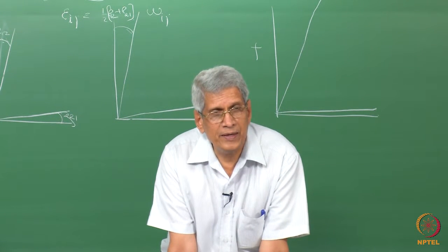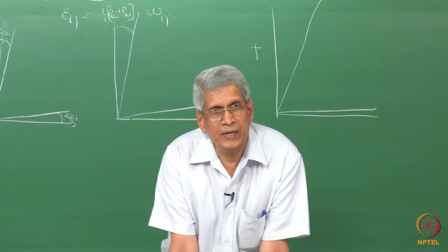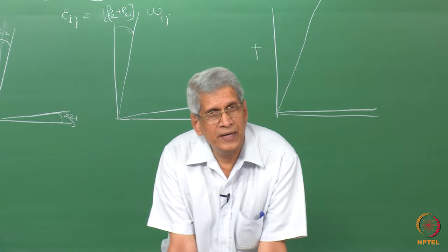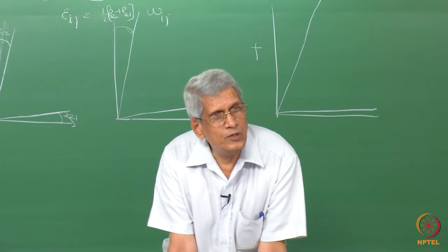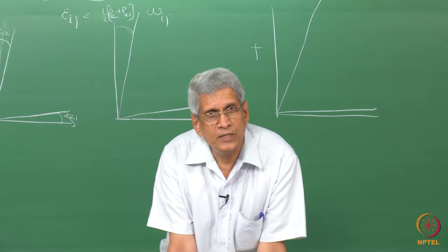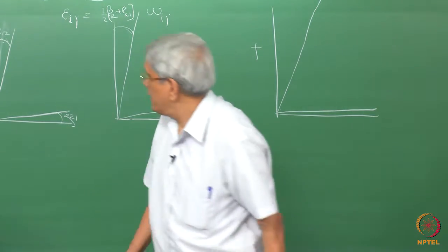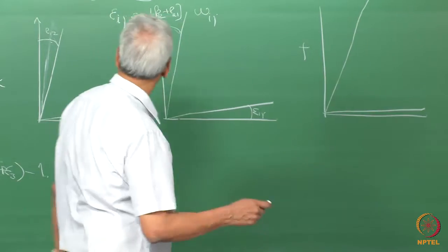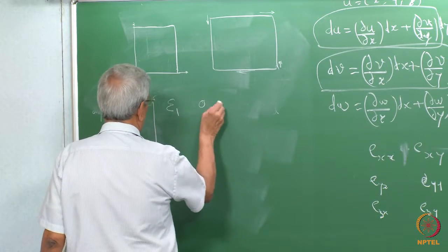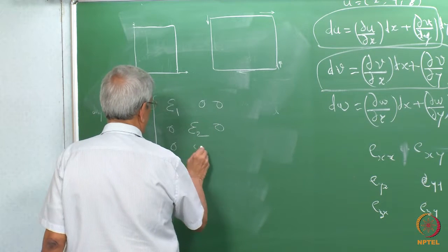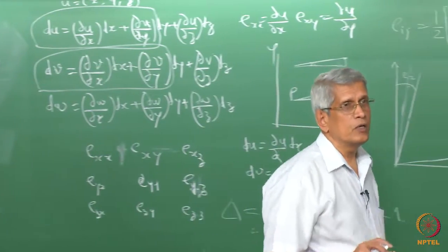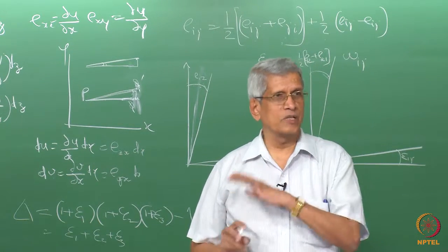when we have a symmetric second rank strain tensor matrix with 6 components, choosing an appropriate axis, we can convert this into just pure strain along 3 axes, with which the same shape and volume change could be achieved. In such a case, the matrix becomes these diagonal elements, which represent only pure strain along these principal axes.